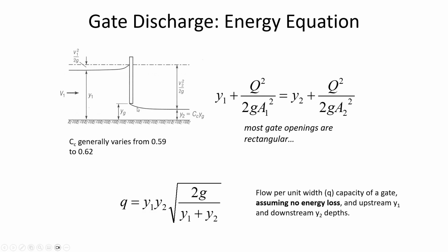And this vena contracta, which means that the flow is continuing to contract after it goes out from under the gate, can be described by here the coefficient of contraction, C sub C. You may remember that we talked about the C sub C when we did the orifice lab in fluid mechanics last semester, where the water was coming out from those little circular holes and the jet was going out. There was a coefficient of contraction there as well, where the jet diameter is actually smaller than the orifice diameter.